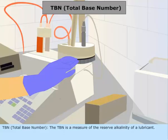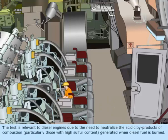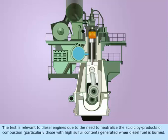TBN, total base number. The TBN is a measure of the reserve alkalinity of a lubricant. The test is relevant to diesel engines due to the need to neutralize the acidic byproducts of combustion, particularly those with high sulfur content, generated when diesel fuel is burned.